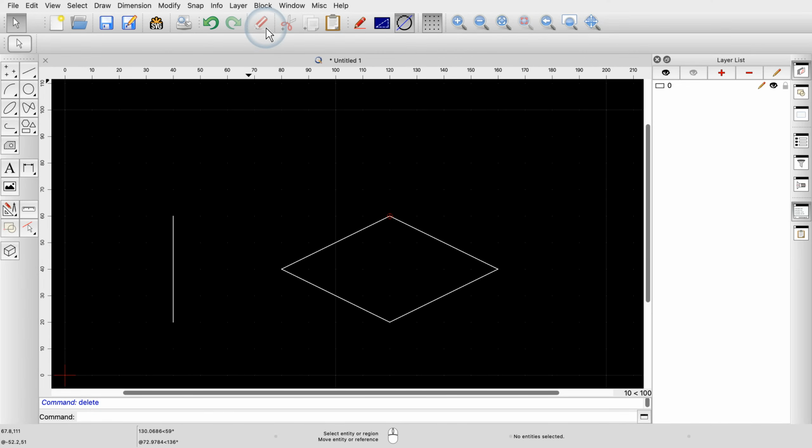There are many other tools in QCAD that can only be applied to a selection. For example, also the tools to cut or copy entities. For this type of tools, we need to first prepare a selection of entities. Without a selection, the tool buttons and menu items for these tools are inactive and shown in gray to indicate that the tools cannot be run without a selection.